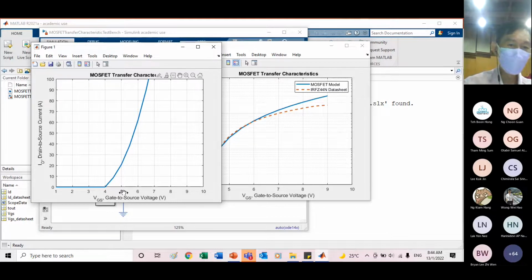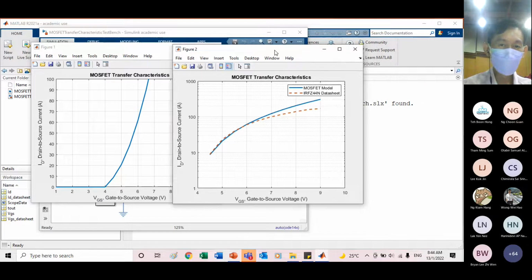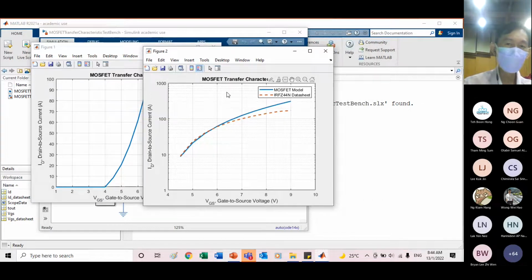And you apply 5 volt, which is the common one we use for Arduino output, yes, it can turn on, but not fully on. But it's good enough for many applications because you can see that at 5 volt it almost reaches 20 amp, so your circuit can supply up to 20 amps. These are what we call the output or the transfer characteristic of a MOSFET.